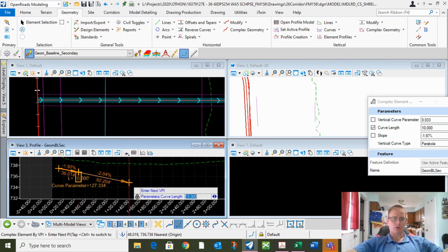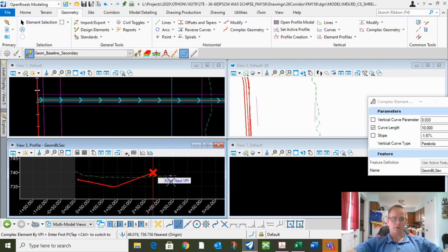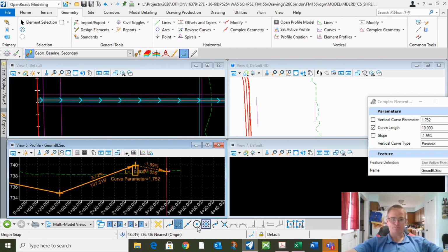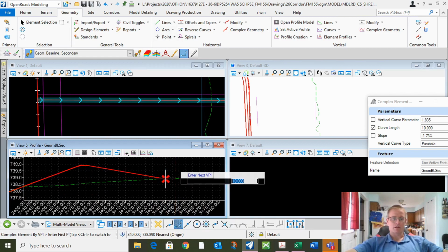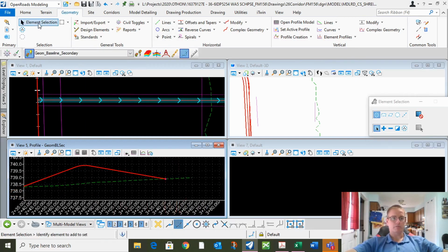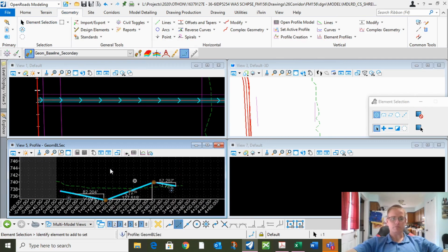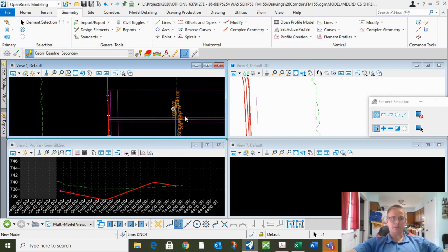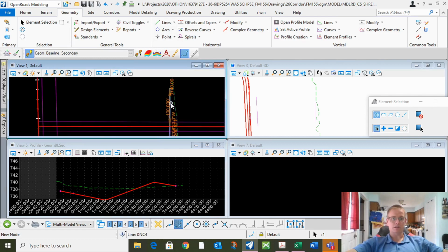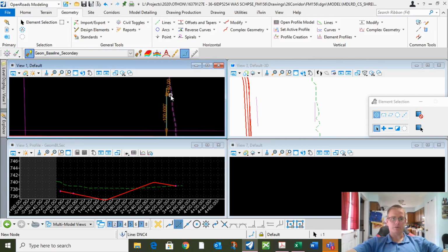And then we said we had a low point and a high point, and we'll tie back in. Make sure again we use that snap on that point. You'll know you have the snap. Click on it, it'll show that little icon. What that does is, if I decide that this needs to be somewhere else, at 340, let's say, we can change it, it's going to go to 300.